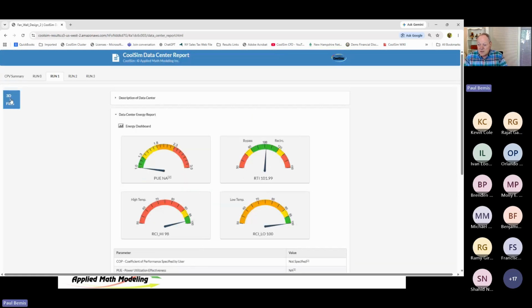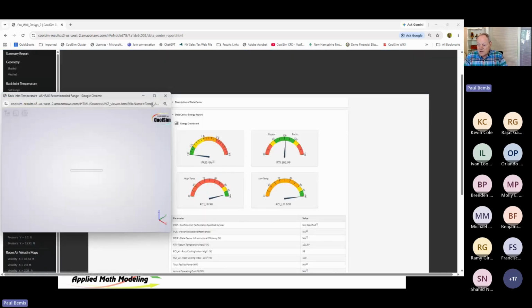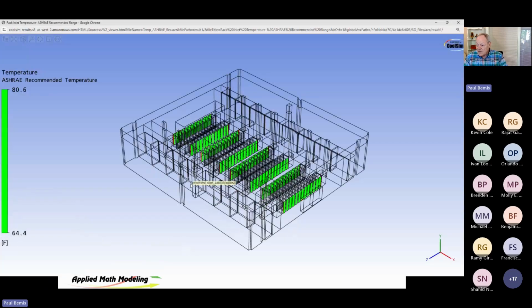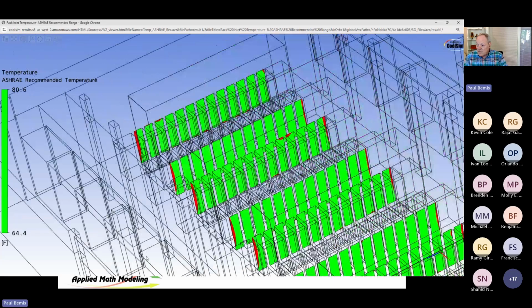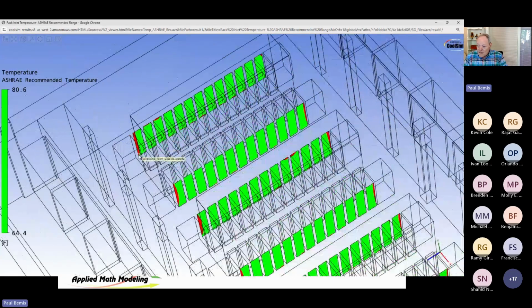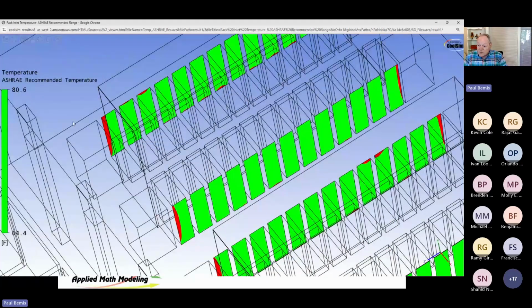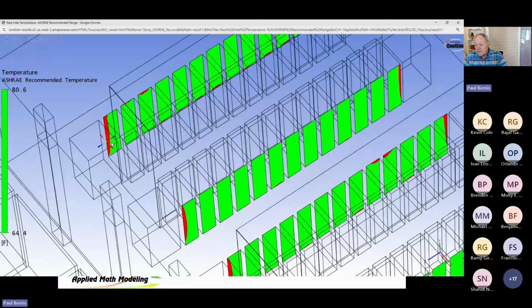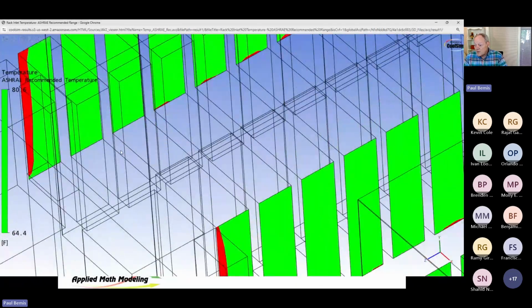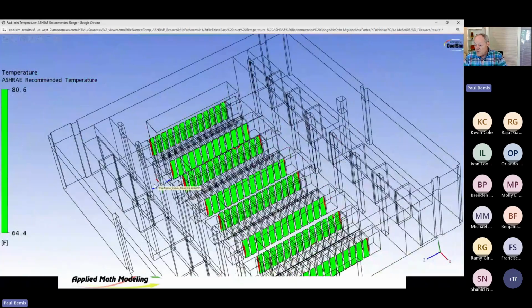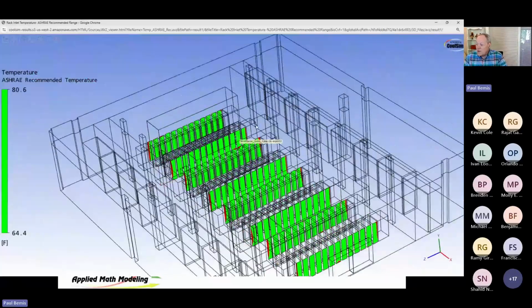But let's go look at the details. Let's first of all see where it's falling out of compliance. And you can see right back where I was earlier, edges. Why? Because that pressure differential is highest near the air handler because I have high velocity air rushing by there. And depending on the symmetry of where that unit is off, that will change.